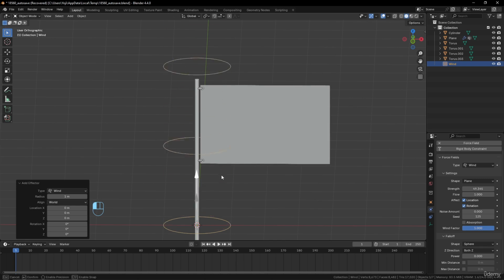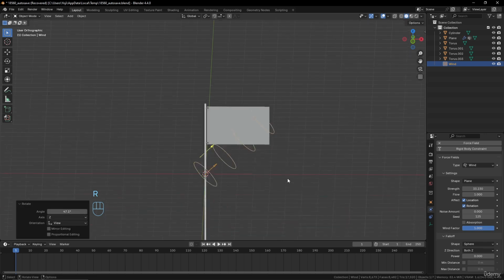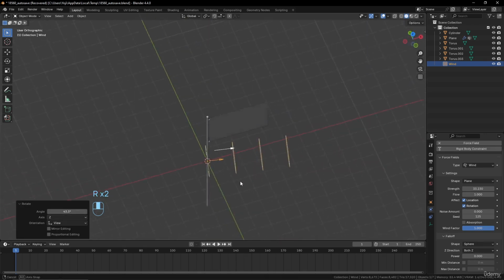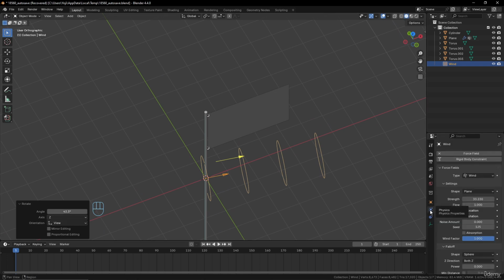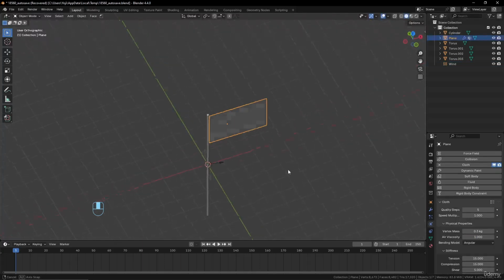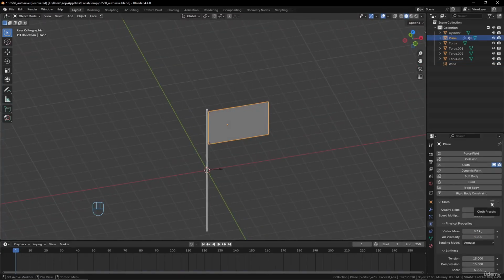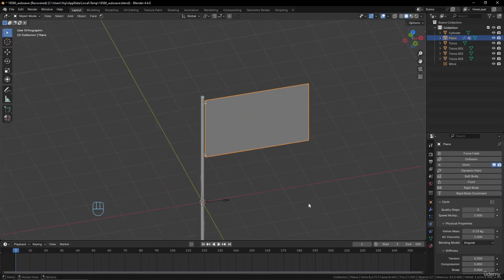You can see it's a basic wind with a direction here. I can increase the strength of the wind, or I can just go and make the rotation look how I want. Like for example, I would like something that goes, yeah, let's say somewhere like that. And you have the options here into the physics tab, the strength of the wind. So directly I can go over 500, I would say, to have something really strong. And I can play after with the settings of the cloth here to have something lighter. So maybe we can play with the silk and see how it will look already.